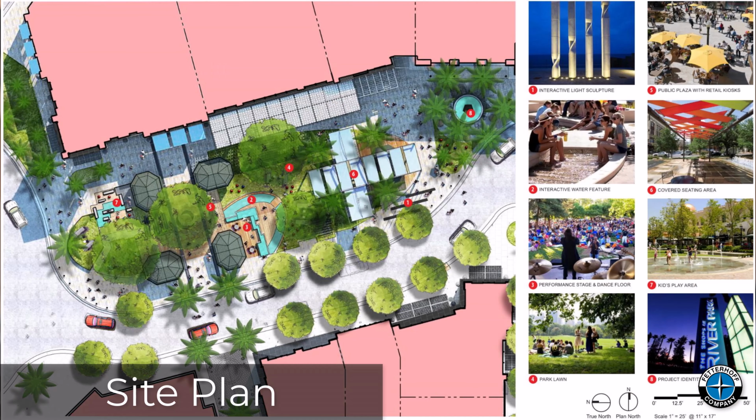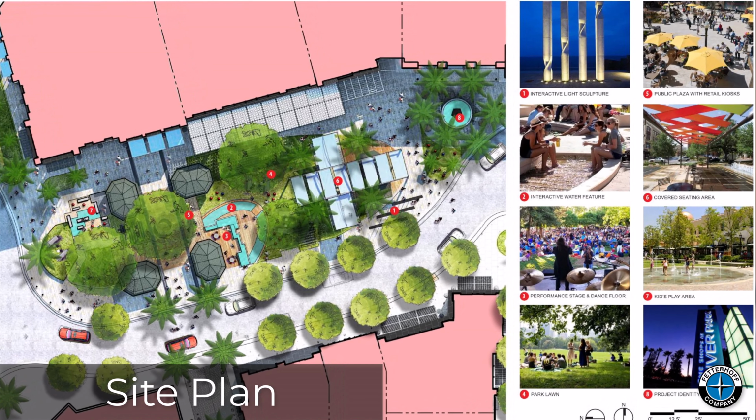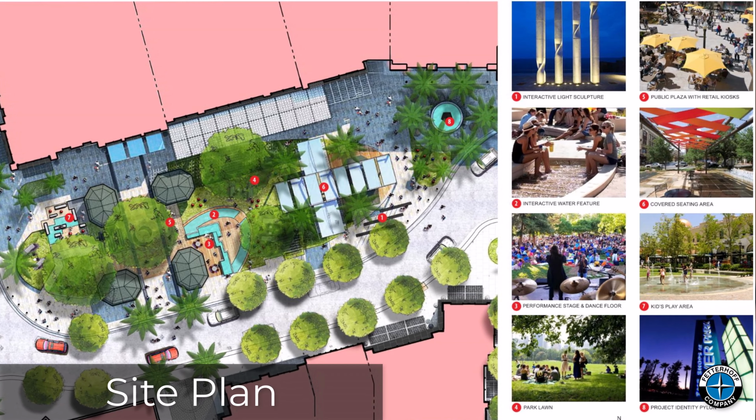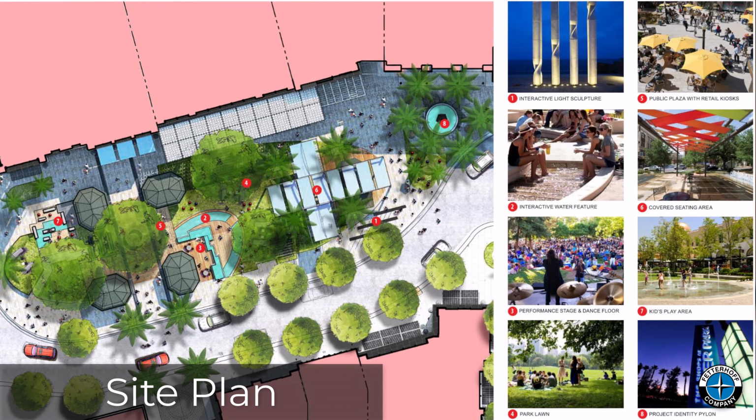A site area study is just a close-up view of a portion of the site plan. You use this to analyze select areas. This is an example study of an outdoor entertainment area. It's supplemented by a photographic image study on the right. This image study is just a collection of existing photos representing the design intent. These photos are a quick, cost-effective way to provide further detail to the design so you can start pricing it out.